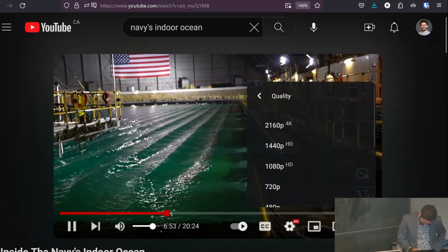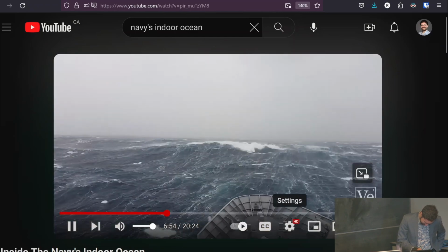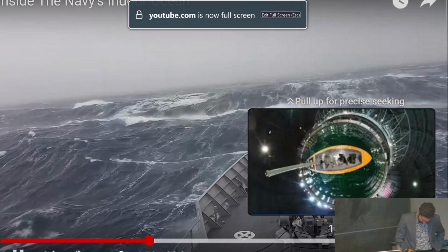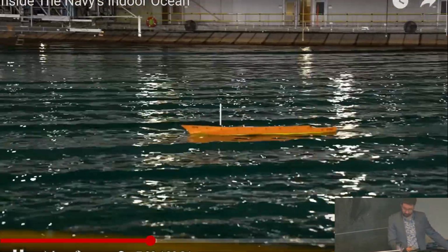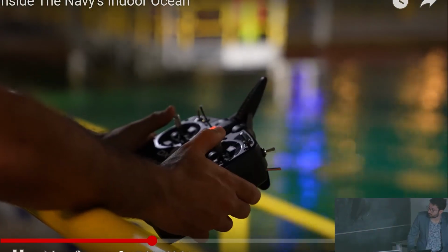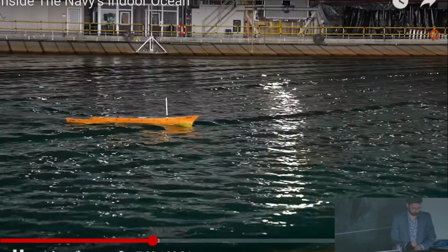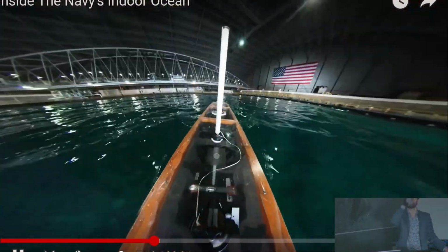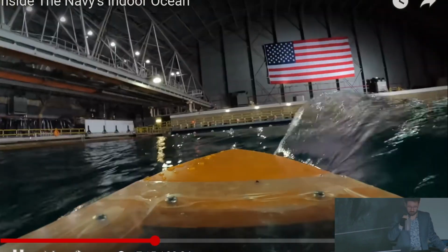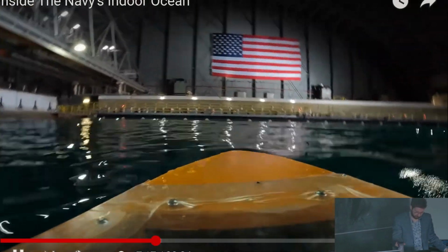It is to replicate on a small scale the types of waves Navy ships will encounter in the oceans of the world. Research engineers place ships modeled after billion-dollar vessels in the water to see how different designs actually behave in real-world conditions. Right now, this is coming from 45 degrees. It's going to be about a 5-inch significant wave height, which if we were to scale it up for this model would be 20-foot waves.